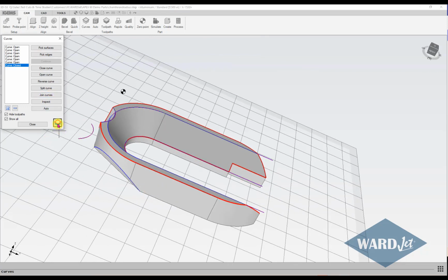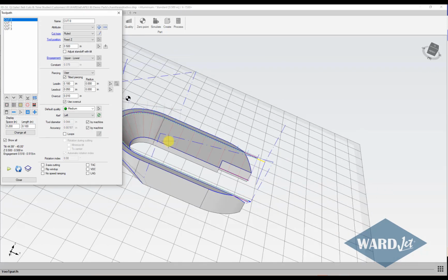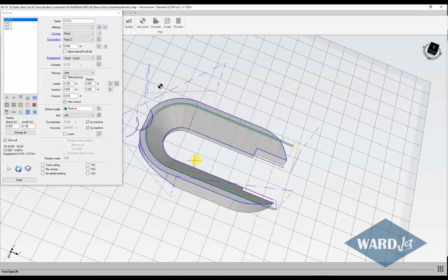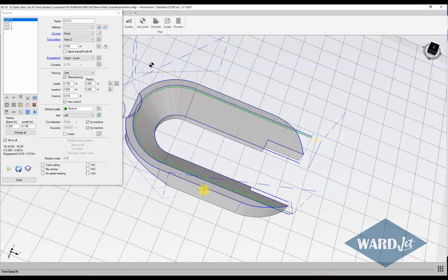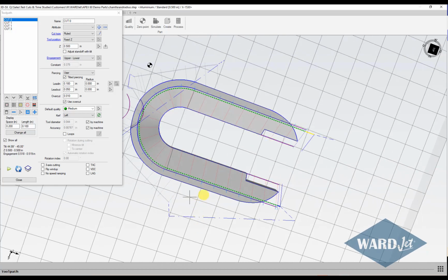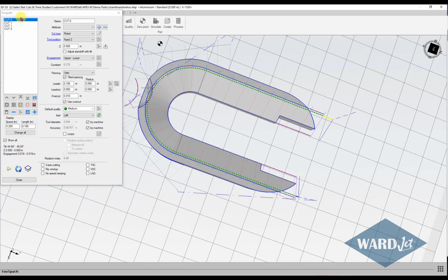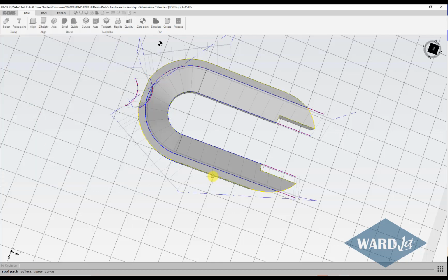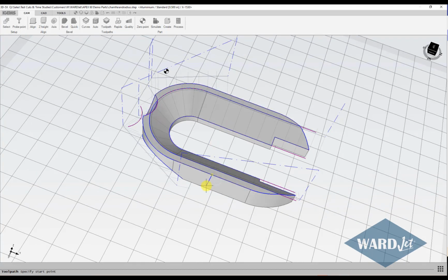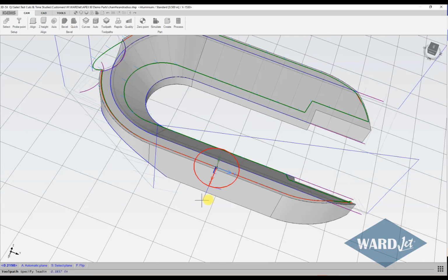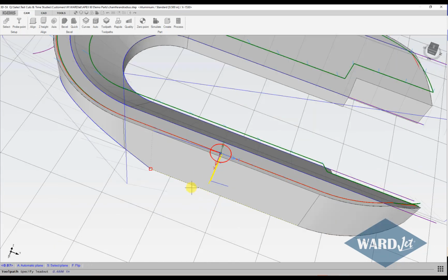And we'll go ahead and add a toolpath to that. So I'm going to leave a tab on this part so it doesn't drop into the tank. I'm going to lead in from this edge down here, and we'll put our tab at our lead in, lead out point down here. So we'll do our plus button, upper curve, start point, end point. I hit enter because I'm going all the way around this time. Direction that I want to go around. Lower curve, I didn't choose lower curve, so I'm just going to hit enter, and then lead in, and then lead out.